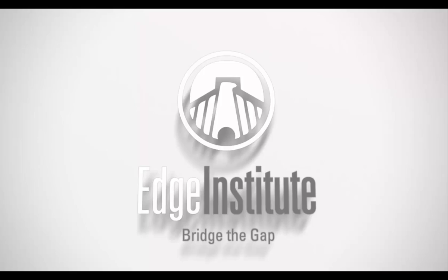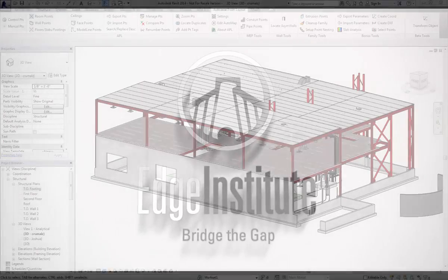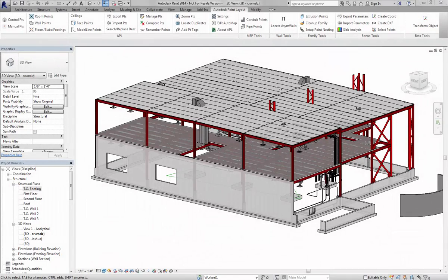Today we will be discussing Autodesk Field Layout. The final step in the field layout workflow is managing the previously placed points, cross-checking and comparing the points taken in the field versus the points coordinated in the model, and reporting on those differences. We begin this process by importing the points that were taken in the field and compare them to the points that we have in the 3D model already.